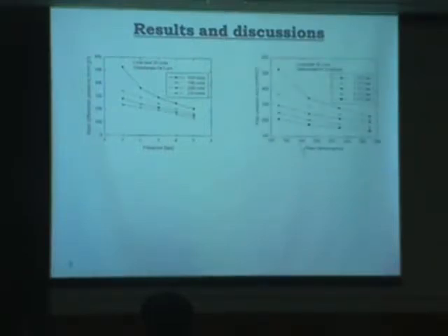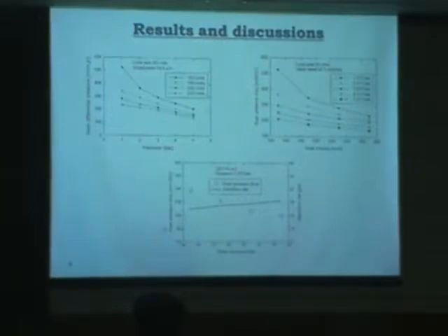Similarly, when we increase the gas velocity at different pressures, the same result is obtained: a decrease in riser pressure is observed because of the widening in the riser system at every pressure. It is smoother at high velocity, and there is more difference at low pressure and low velocity. And for the 120 micrometer glass beads, the same result was obtained when we increase the riser velocity: there is an increase in the solid flow rate and a decrease in the riser pressure.